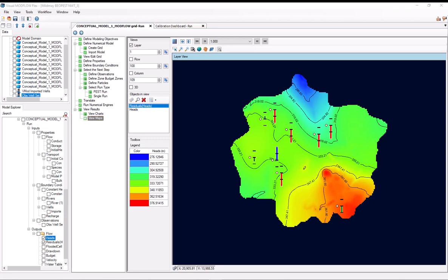the MODFLOW NWT engine. In the MODFLOW 2005 engine, as well as many other MODFLOW engines, cells can be turned dry and inactive if the head is below the bottom of the cell. This can cause stability issues, and as you can imagine, in a PEST run where there might be thousands of model runs, each with slightly varying parameter sets, it's quite common for PEST to run into some parameter combination that causes instability, which then causes problems during your PEST